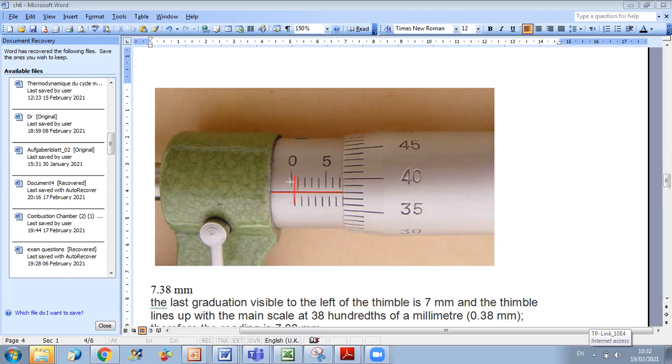This is why, for example, here we annotate the rotary symbol from 0 to 50. We have 50 divisions. Okay, this means that we are dividing 0.5 into 50. We are dividing the 0.5 millimeter, which is the smallest reading in the main scale, into 50 divisions.